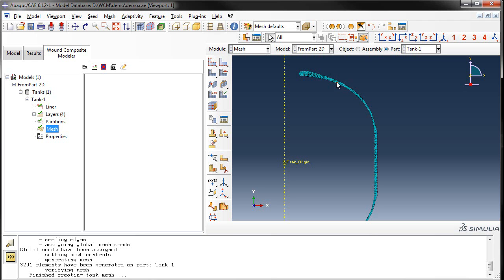And you see these are woven together. So they're basically at the same coordinate through the thickness, but they are woven. The fortunate thing about that is that we can assume that the behavior of that is axisymmetric. Now, to run an axisymmetric analysis in Abaqus, you have to have the material coordinates in the global direction. So two of the axes have to be in x, y, and the third has to be exactly in the z direction.